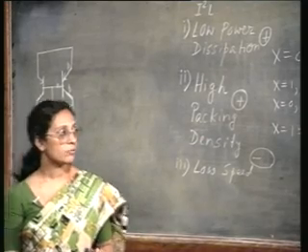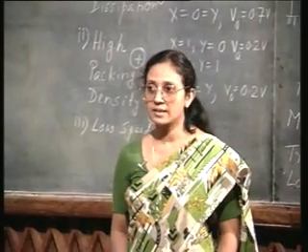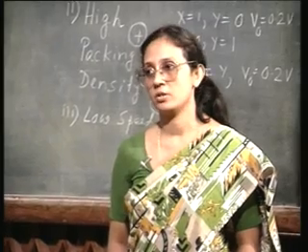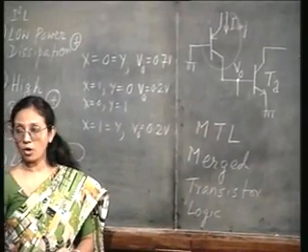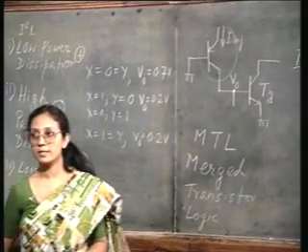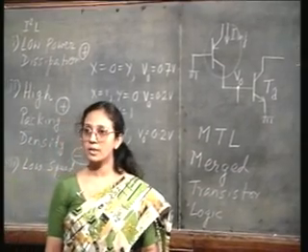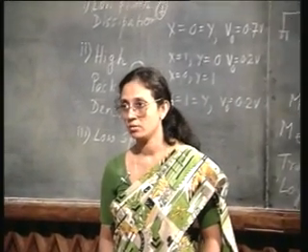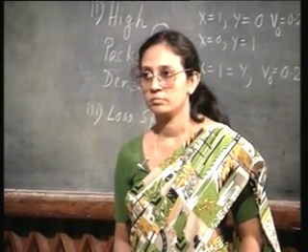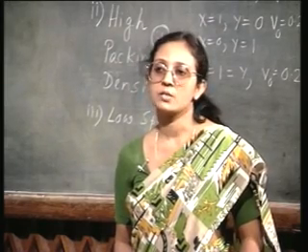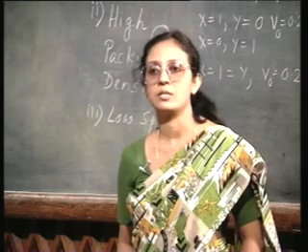Okay. Now, from the technological point of view, I square L circuits have another advantage: basically you do not need any isolation. Why? Because remember, all the blocks, whatever I drew here, had grounded base for the PNP transistor and grounded emitter for the NPN transistors. Therefore, I do not have to isolate them, they can all share the same substrate. The substrate can be grounded and all the transistors can share that same substrate. So, strictly speaking, in I square L, isolation is not necessary. You do not really have to have an isolation.